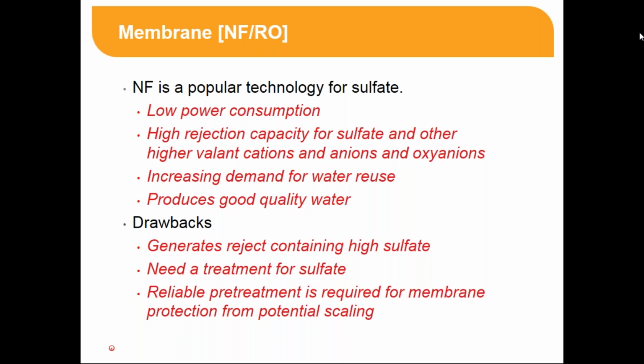but its advantage is it passes the sodium and chloride, or monovalent cations. The advantage is you don't build up the TDS. And also the power required to operate a nanofilter is lower compared to reverse osmosis. Reverse osmosis rejects almost all cations and anions. Wherever you have a reuse application, nanofiltration is a very good technology to reduce sulfates to very low concentration, and your effluent quality is very good.